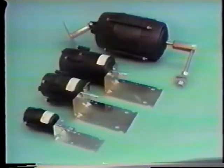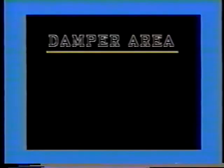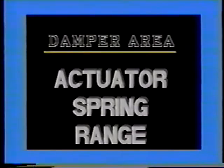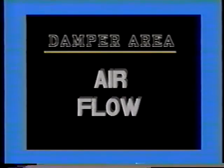Robert Shaw offers 4 distinct sizes of damper actuators, generally referred to and selected by stroke length. These actuators come in 2, 3, 4, and 6-inch strokes. The larger actuators have a greater diaphragm area, allowing them to handle larger dampers. The actual amount of damper area that an actuator can handle is dependent upon the spring range of the actuator, quality of the damper construction, and the rate of airflow across the damper.